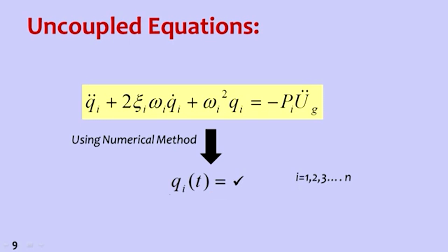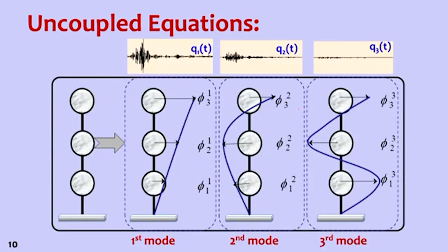As many degrees of freedom as there are, that many time history responses we find for a given component of earthquake ground motion. So as you can see, this is the total response. So this is U1, this is U2, this is U3. The Q1 we found just now is this Q. We are giving input ground motion somewhere here, time and acceleration. With this we decoupled the equations in 3 mode shapes.